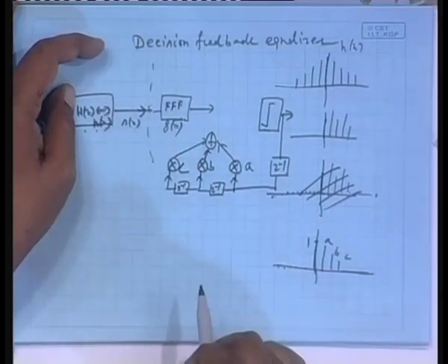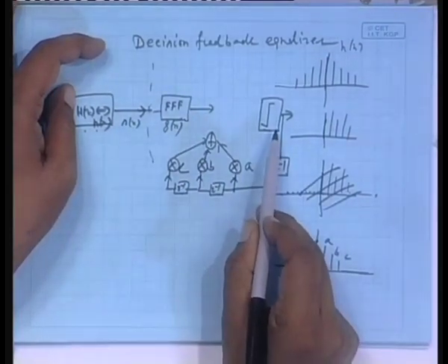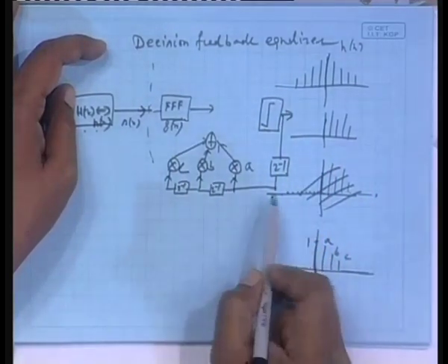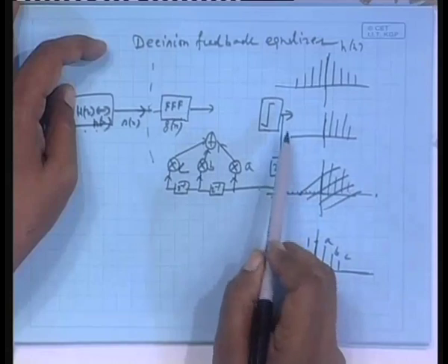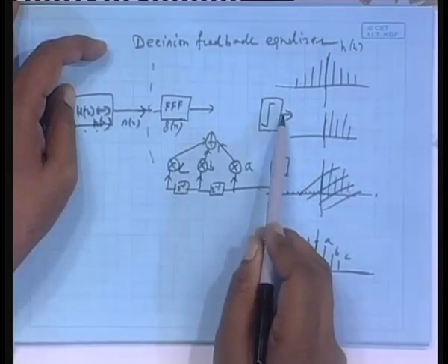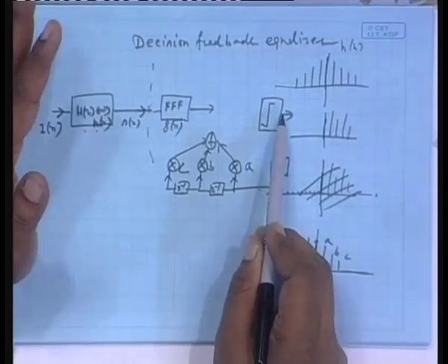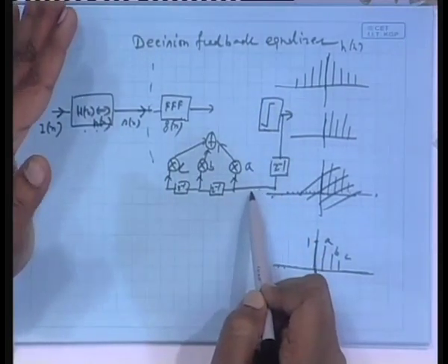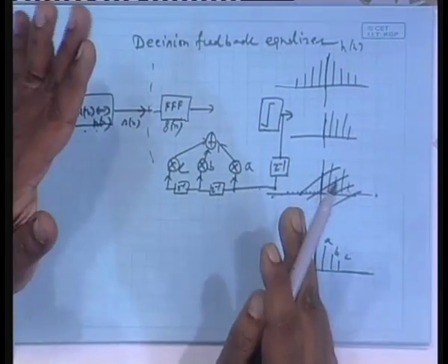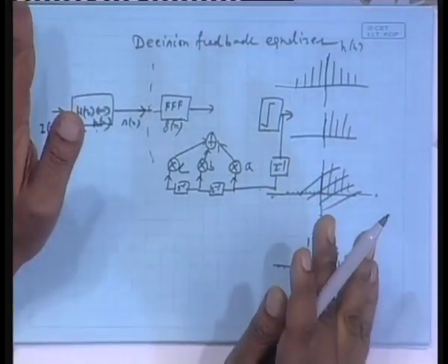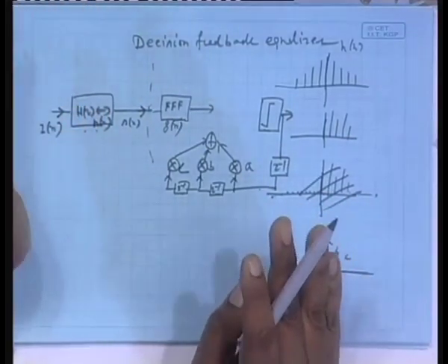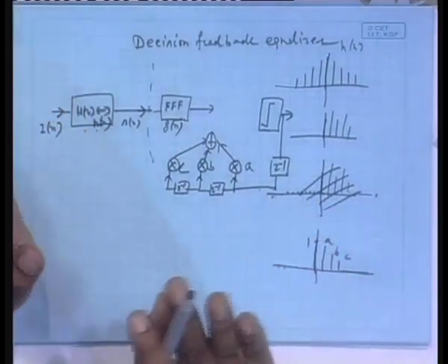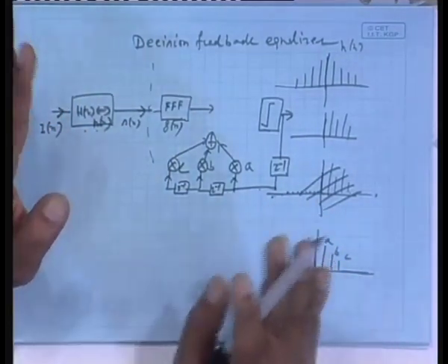What does it mean? Suppose past decisions are correct, suppose till this point of time your past decisions are correct. Right now you will make a correct decision, present decision, that I am coming to later, but after this delay here past decisions will come. Suppose past decisions by hook or crook are correct, say they are indeed correct values of I n which were transmitted and detected like that, at least past 3.